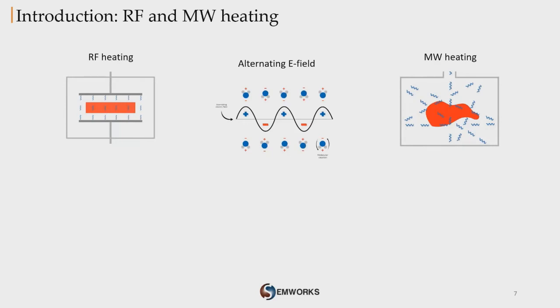These two high-frequency heating technologies work in relatively the same way. Heat is generated when the product is passed through an alternating electromagnetic field due to the product losses. This electromagnetic field creates vibration and rotation in the polarized molecules inside the material, so this friction between molecules increases the temperature of the heated part. Both technologies are based on volumetric heating, and the main difference is related to their wavelength and operating frequencies. RF heating operates from 3 kHz to 300 MHz, and microwave operates from 300 MHz to 300 GHz. Now what about the applicator design of each type?